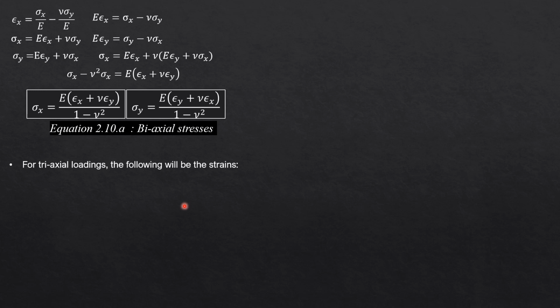So after we apply the superposition method, strain x would be sigma x over E minus Poisson's ratio over E quantity sigma y plus sigma z. So that would be 1 over E quantity sigma x minus Poisson's ratio quantity sigma y plus sigma z, rather. Then strain along y.